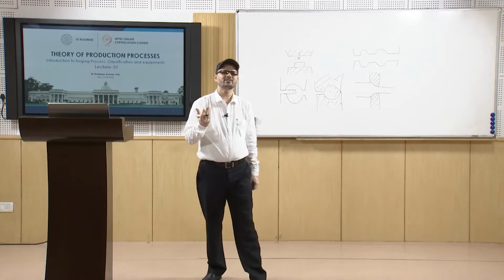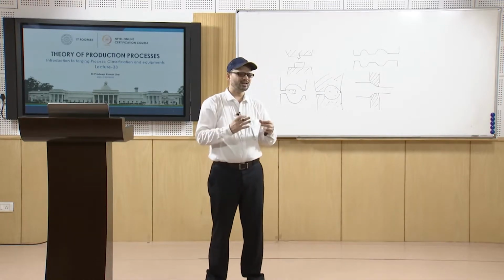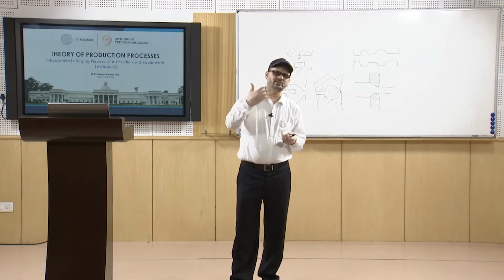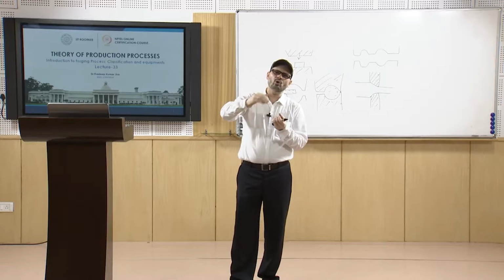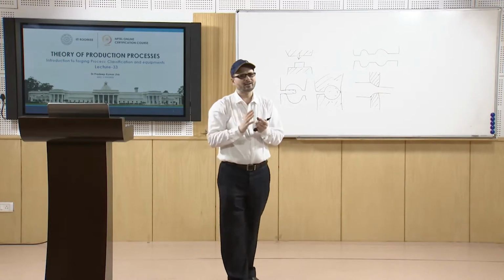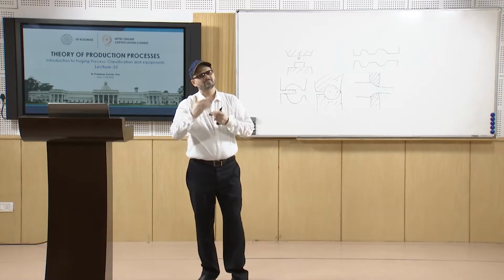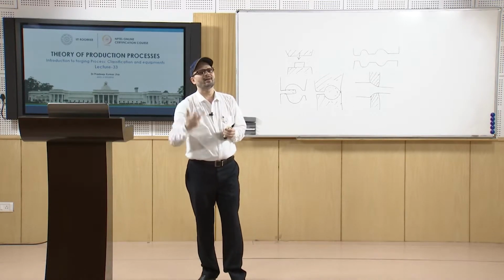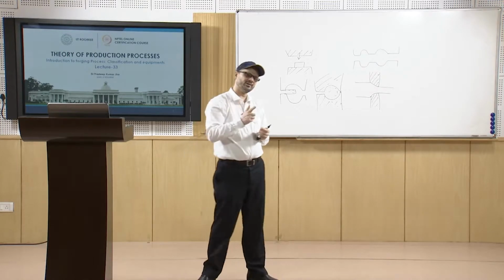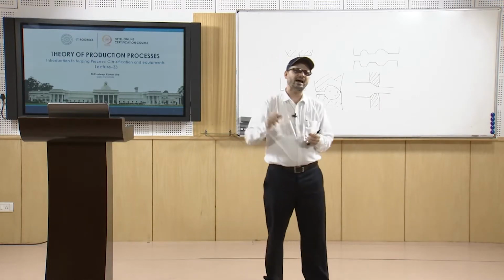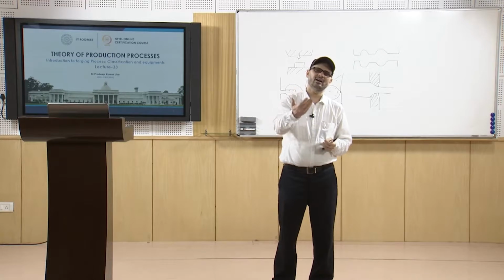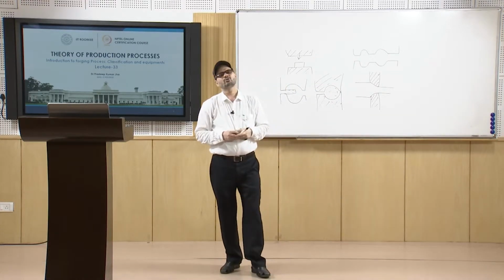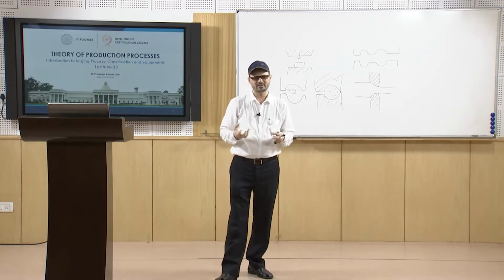Blocking means it is a semi finishing operation. Stage by stage the material will go into different dies, and slowly the shape of the product will come closer to the final shape. When the material comes out of the finishing die, then the material is ready. Before that it has to come to the blocking die, which is the semi finishing die.